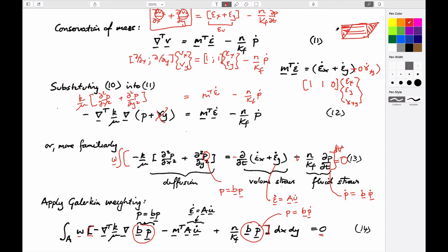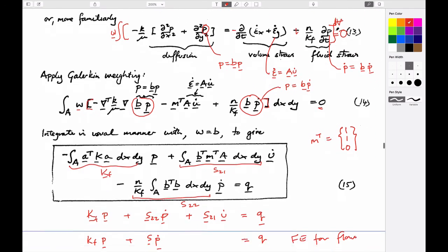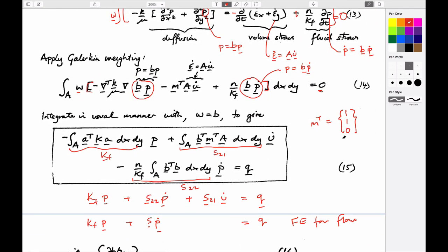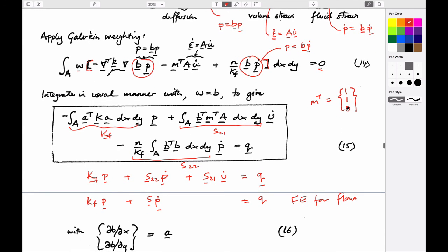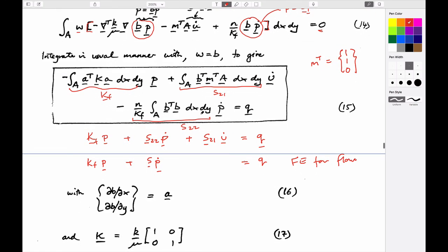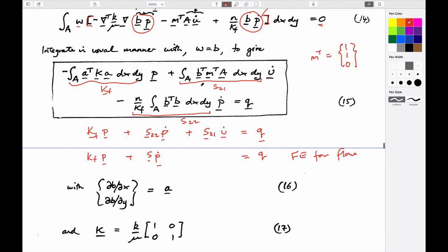And so when you apply shear stresses, there's no net volume change in a linear elastic system as a function of that. And so that's the reason that this term here, in the same way that when we look at effective stresses, shear stresses aren't operated on by fluid pressures, shear strains don't cause a net volume change, and so this 0 is appropriate there. And so if we dissect this term that allows us to get this volume change, this is the strain displacement matrix.